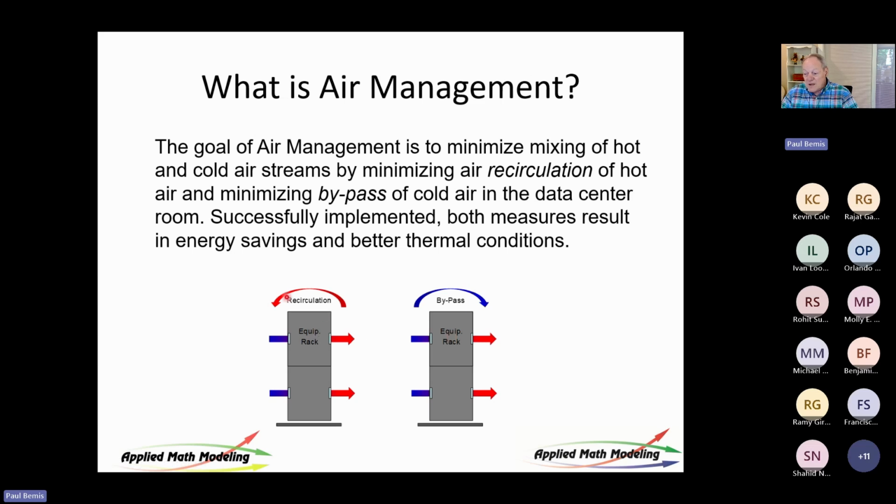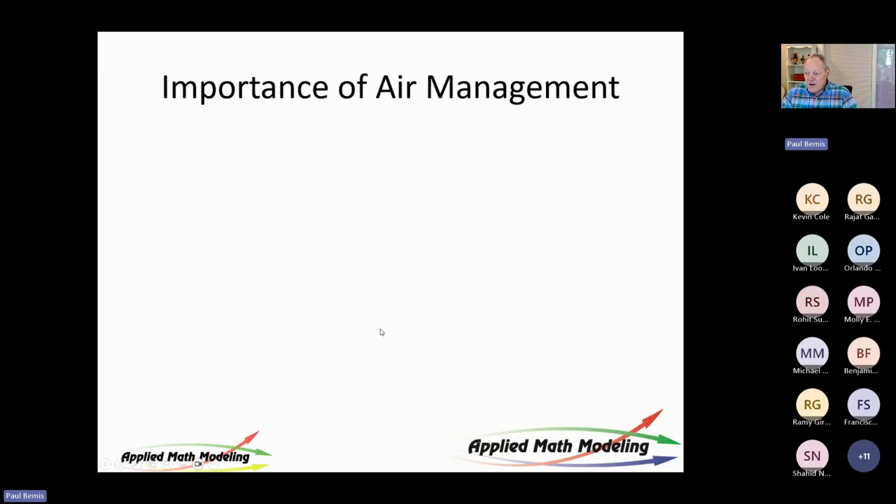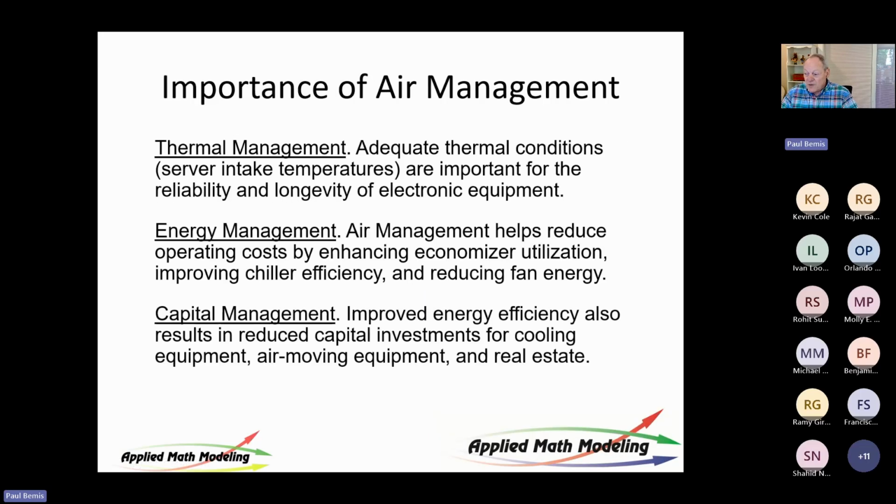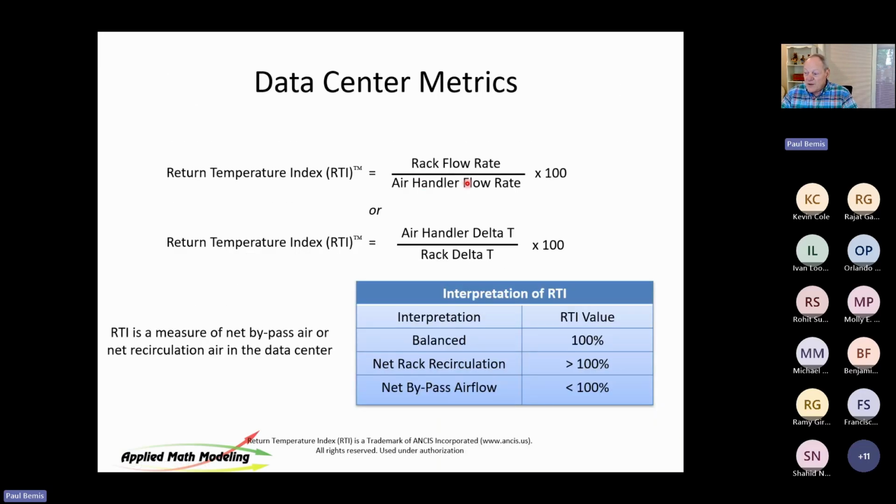If you're below what the rack appetite is, you're going to have this situation. That's going to result in hot spots. You're going to have reliability problems. Furthermore, this rack will start to ramp up in speed. Its fan speed will come up once it senses high intake temp. So to have a high bypass airflow, you need to have this one greater than that one.